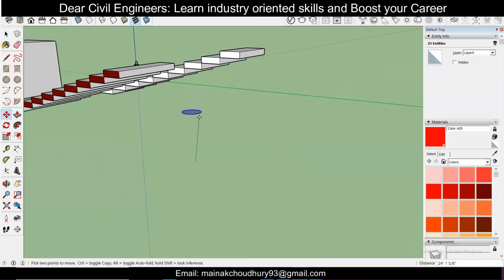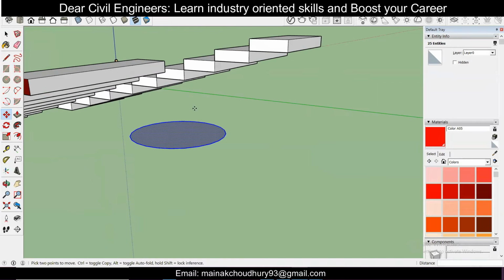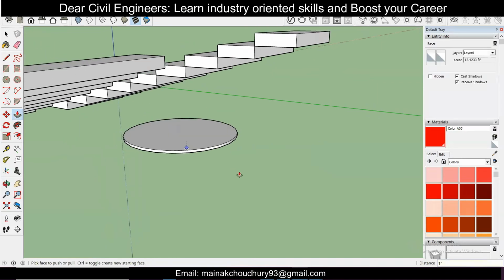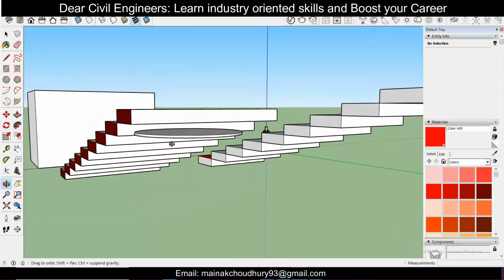If you want to move it on the blue axis, I'll just press the up arrow and move it up a little bit. Okay. And after that, I'll just use the push pull tool here to give it a particular elevation. Let's give this, let's say, 1 inch. Okay. And after that, we want some legs in this particular table here.